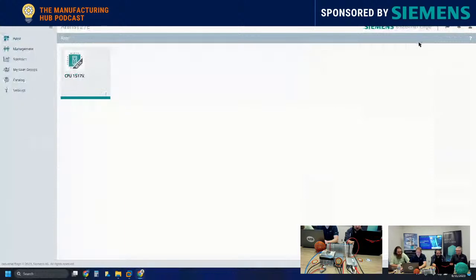So that is going to be a virtual PLC, and I'll let the two of you elaborate on that a little bit, but that is equivalent to an S7 1500 series and is capable of running the code that you would develop in TIA Portal, correct? Yes, with some nuances. It's a very young product for us. So it is a 1500 PLC through and through. It acts like a 1500 PLC. It programs like a 1500 PLC. You use TIA Portal to program.